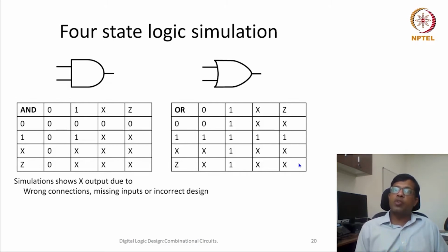Because in Verilog, whenever we declare any particular signal as wire, or as register, reg, Verilog implicitly assumes that these are the 4 states of the signal which are possible. So these 4 states are implicit in Verilog. This is trying to represent what a realistic scenario would be.